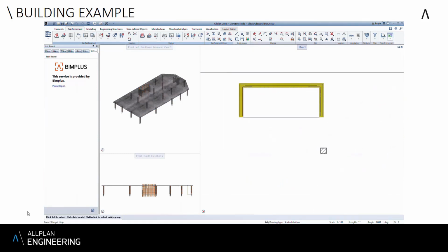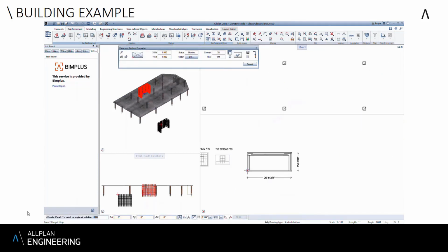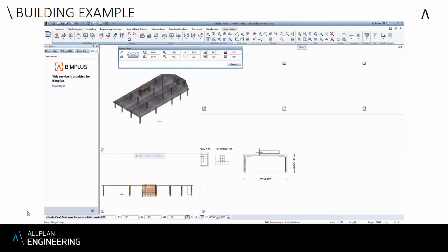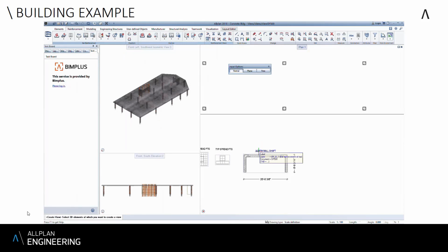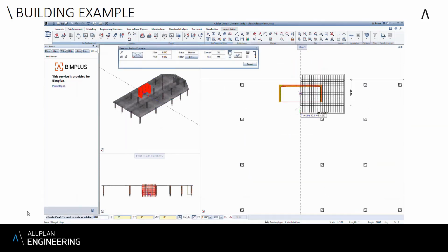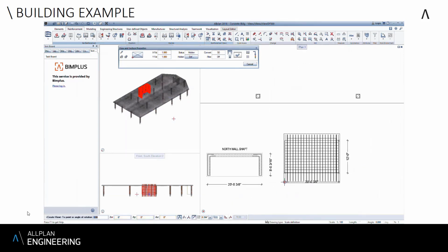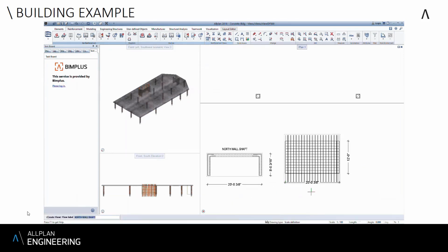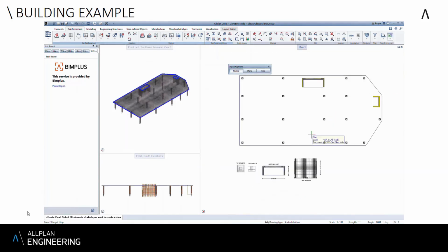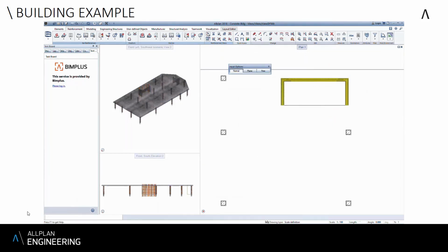So I'm going to go ahead and just do the same thing, but now for my wall shaft here, maybe this core wall, I just want to show some information there. So I can take just a quick plan section of that, and then I can do an elevation of the wall. If you want to show an elevation of the reinforcing of the wall, I know I've seen that a lot in customer drawings. And of course, this is a little bit primitive, but you can have some more different bar layouts, some different overlaps. You can fully detail it so that it looks correct, ready for construction. And then we'll do a section there as well.